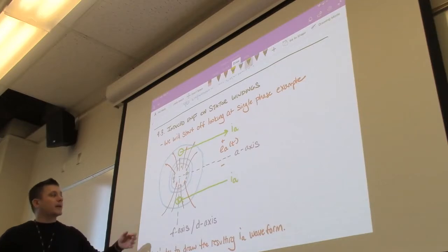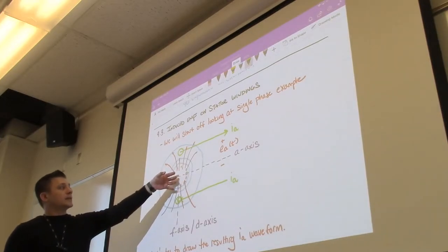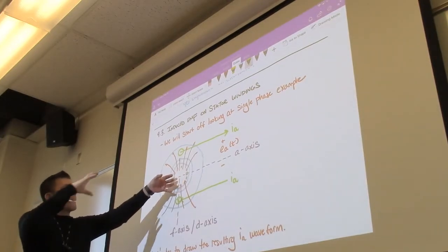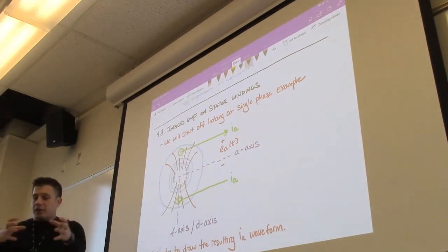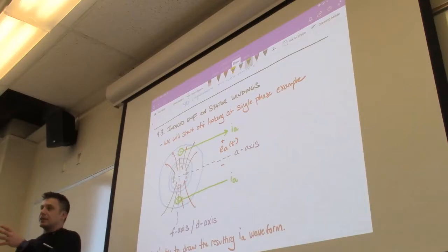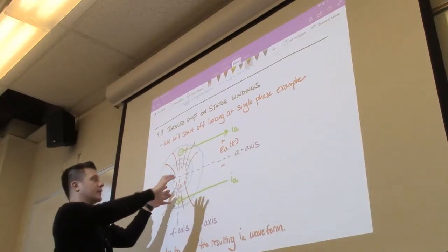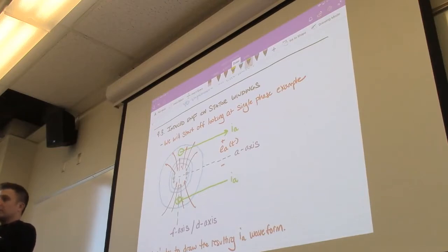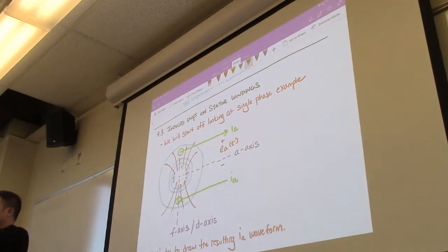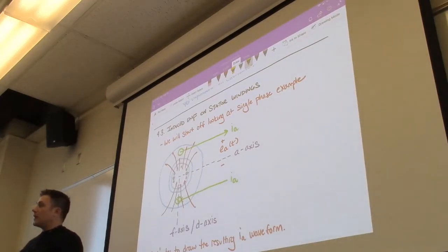So if you think about it, right, this coil looks like this. The other one looks like that, if you can imagine my hand being like a cylinder. This is the worst case scenario, okay, the mutual inductance will be at the minimal value, right? There'll be very little magnetic energy flowing out from the field winding to the A phase.